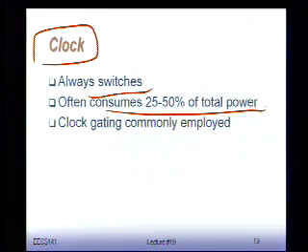The way we're going to do this is, and that's a very important one, it's kind of a little sidetrack. I'm not going to talk more about that. But for instance, if you have a big chip, and certain parts of the chip don't do anything. Let's say I'm not using the multiplier for a while. I have a very complex data path with a bunch of multipliers and ALUs, and I don't use a multiplier. It's a good idea to disconnect the clock from that multiplier. Even if I keep all my inputs constant, if that clock keeps going up and down, all the fan-out capacitance of that clock is going up and down.